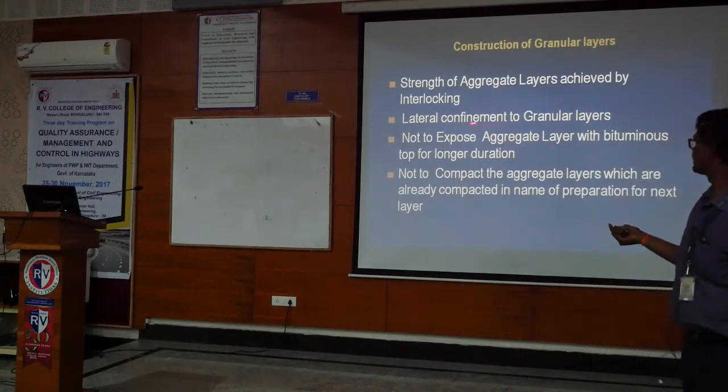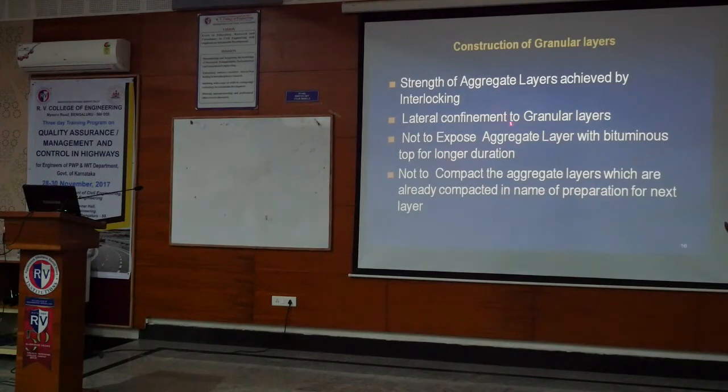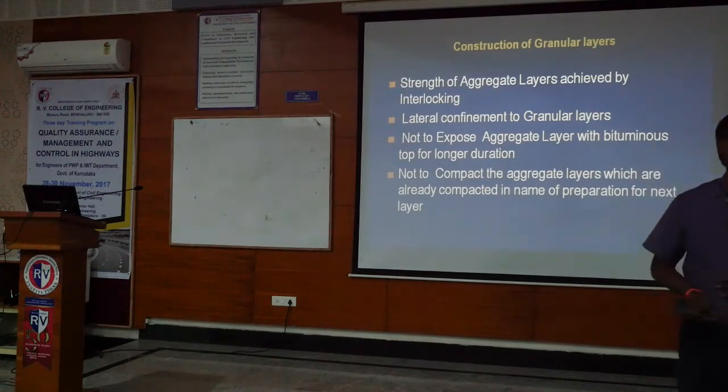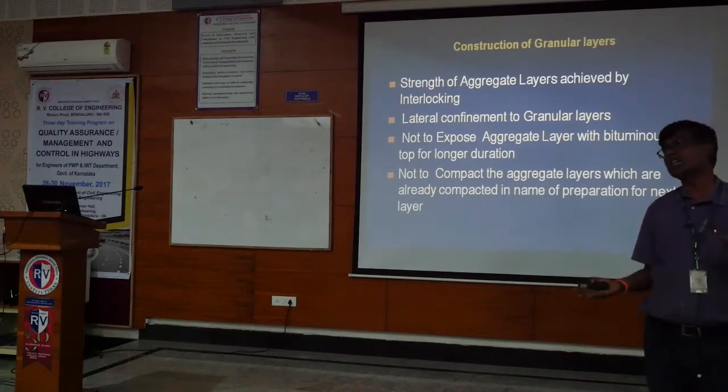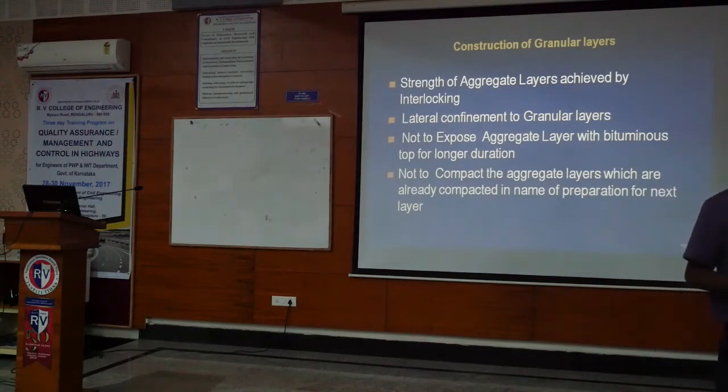It is a practical problem because we don't have service roads or diversion roads, so it gets disturbed. Once I have made wet mix macadam and cleaned everything, but traffic goes over it, it is back to square one. So within the limitations, what best we can do is how early we can go for a bituminous layer covering. That should be the model.